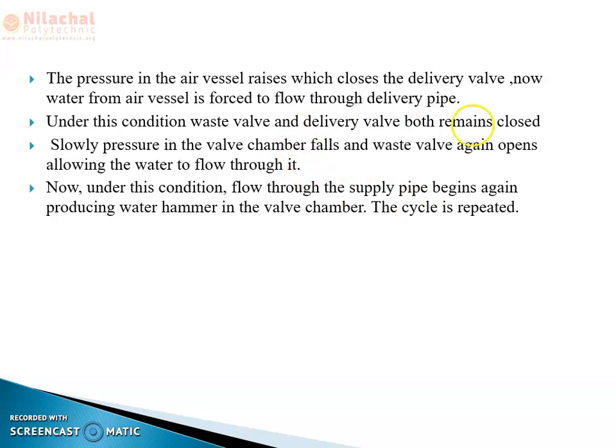Slowly the pressure in the valve chamber falls and the waste valve again opens, allowing water to flow through it. Under this condition, the flow through the supply pipe begins again, producing the water hammer in the valve chamber. The cycle will be continued.